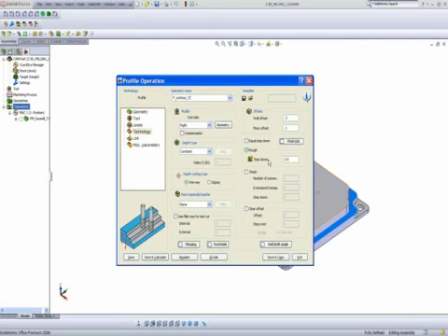And with this particular tool, I can also do a finish cut. So I'll be choosing also to do finish. And I'll be doing it with one pass. And my step down, I can leave this at 0 since I'll be doing it all in one step down for my finish cut. Now we also have something here called clear offset.